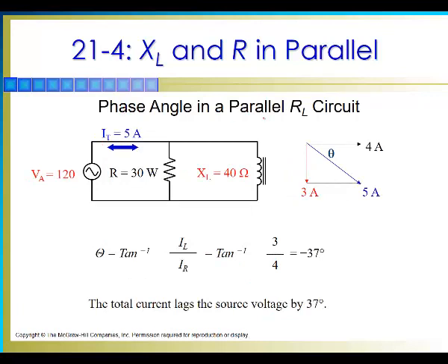The phase angle in parallel is the same thing. We're going to have the current, and we're going to calculate this angle right here. We always take the current on the resistor as base, because that's the one that is in phase with the voltage. So what's this angle?